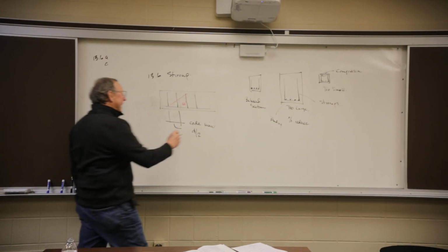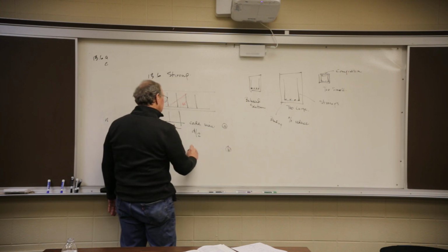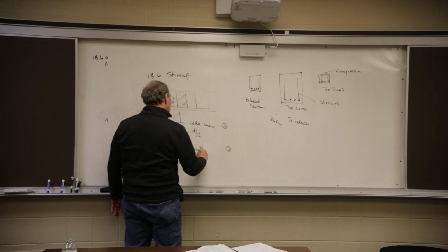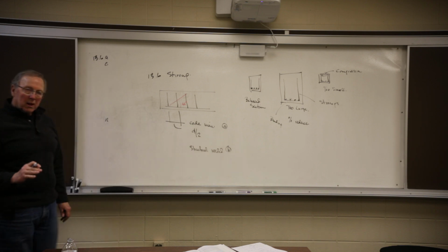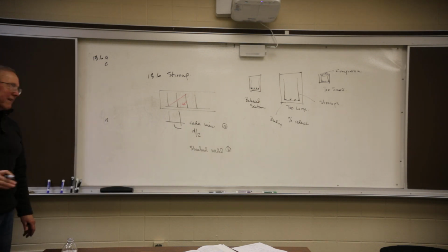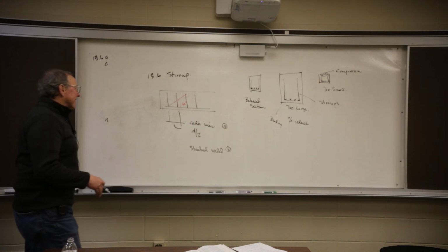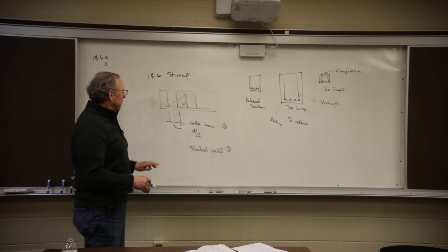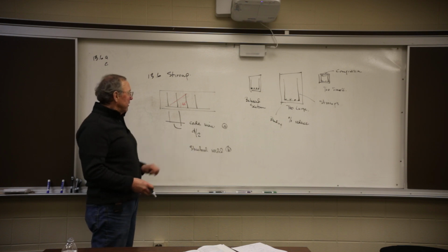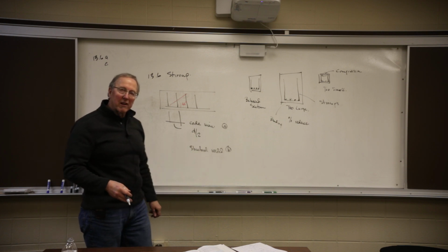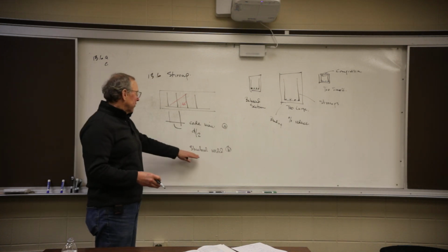So we're going to have A is code minimum, B is structurally needed. So if I need them closer, I have to put them closer. If I don't, then code requires me to put them at D over 2. So the way it's set right now, all I've got to do is determine whether D over 2 works. If it works, I'm done. The second part is if it doesn't work, I've got some additional calculations to do to determine where to put the stirrups in order to make it structurally sound.